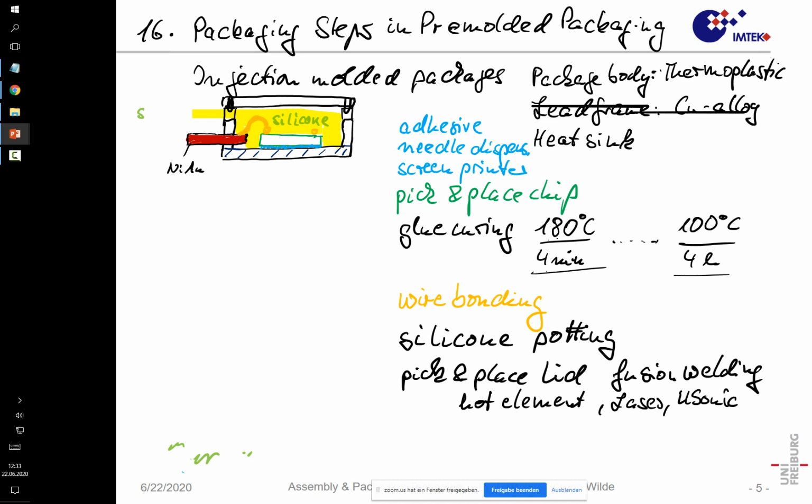If you have a pre-molded package, a plastic material, let's say like PA66 or LCP, that has a very poor thermal conductivity, let's say something between 0.2 and 0.5 watt per meter Kelvin. On the other hand, when you use something like a heatsink of aluminum oxide, that would have a thermal conductivity of 25. So it's 100 times better.